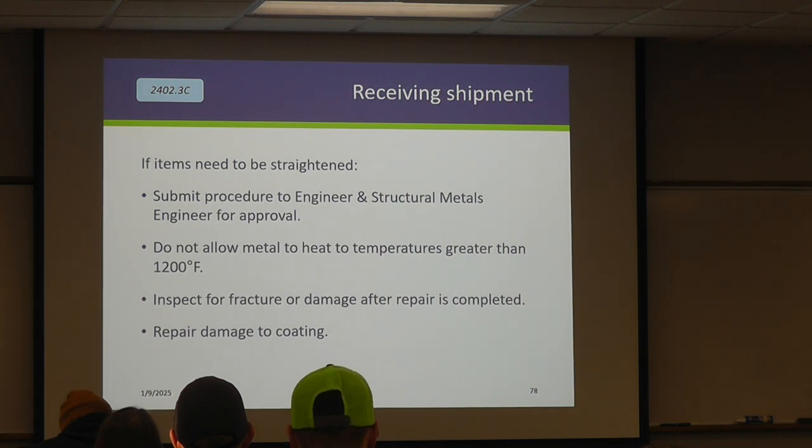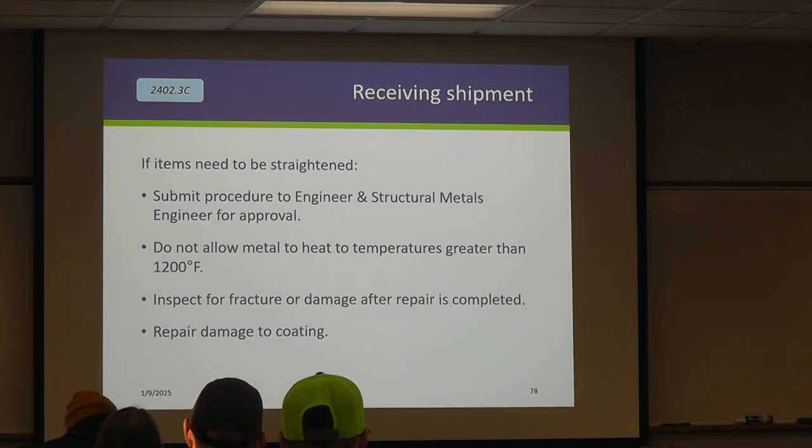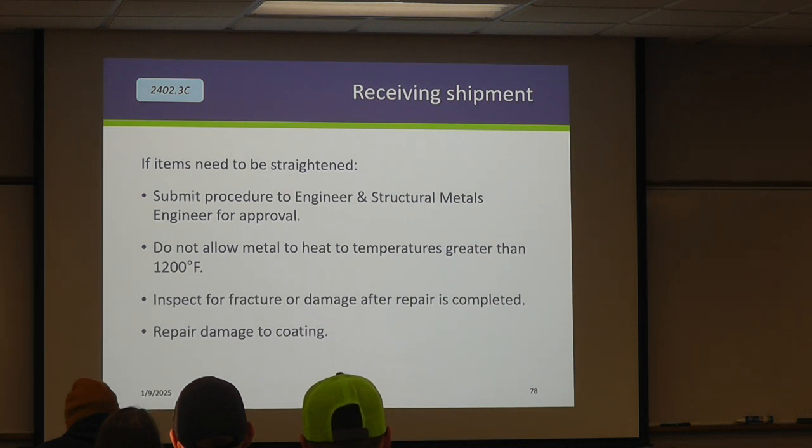The elements need to be straightened. We do permit some level of heat straightening. The spec book has some of these general limitations in here, but the biggest piece I want you to take away from is they gotta have a written procedure that every party is gonna agree to. Heat straightening is much more of an art than it is science. It takes very experienced people to do it right, not Bubba the iron worker with his little fire iron. And so it needs to be well thought through before we go through any of this, particularly if it's an element like a beam that's going to be carrying a significant load. And it's something that we can work through. Just got to get the right procedure.